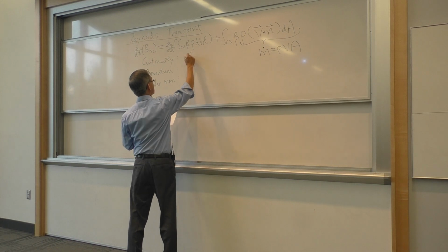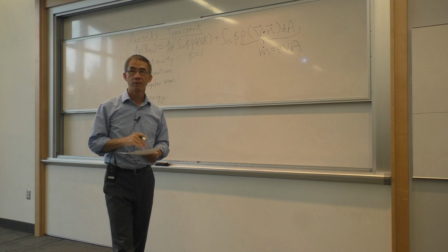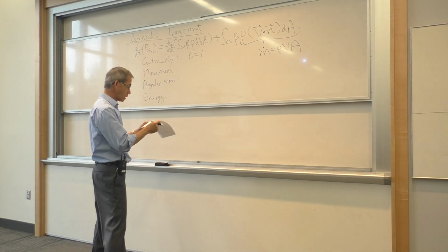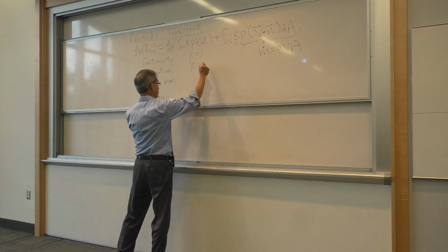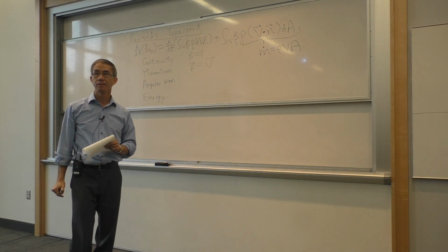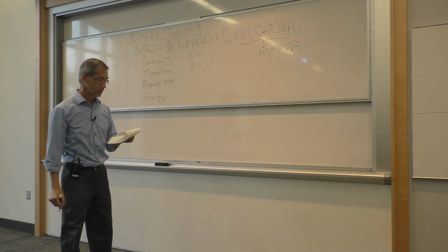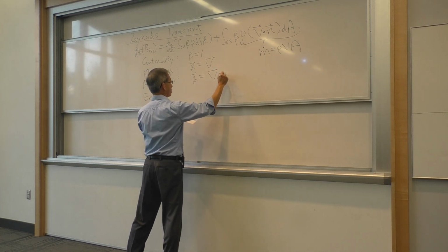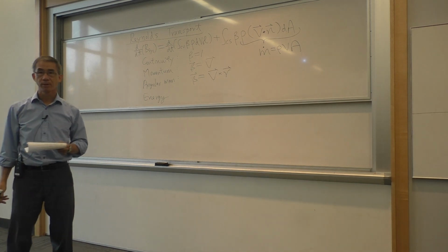So for continuity, I won't go through the derivation. We set beta equal to 1. Beta is the quantity per unit mass. So for continuity, beta is simply 1, and out comes the continuity equation. Momentum: beta is the velocity vector in three directions, i, j, and k, or x, y, and z. Angular momentum: velocity cross product with the radius. Remember all this?